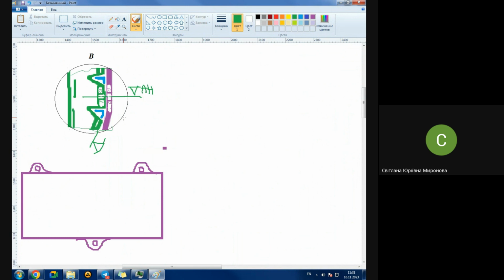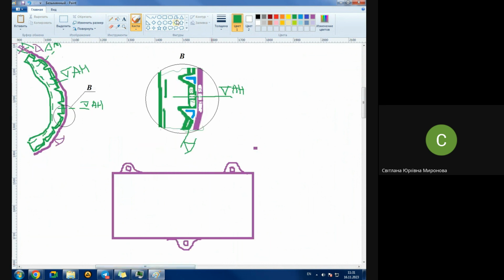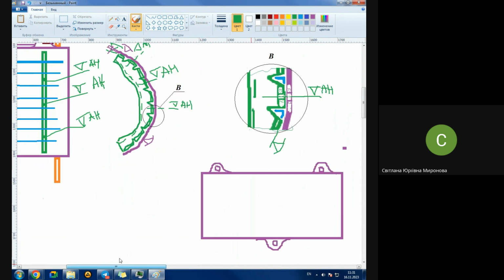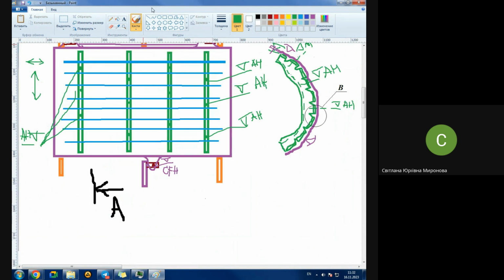Respectable. Stringers. What about stringers? I'm afraid it's the same story. Stringers are going to be located by assembly holes. The only matter you need to solve is how many assembly holes you need in each stringer. In my opinion, there should be at least 4 assembly holes.